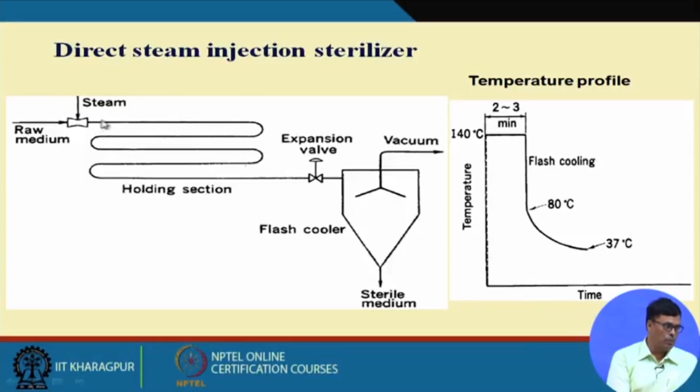The flow characteristics of a fluid depend largely on the viscosity and the density. I can give the example of the Reynolds number: Reynolds number is equal to d u rho by mu.